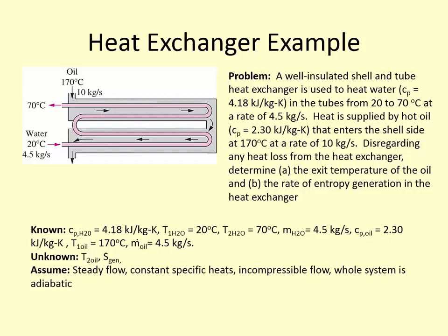So how would we go about trying first to determine the exit temperature of the oil? What will affect the oil temperature? How does it increase or decrease, or what do you think is going to happen? Okay, the water is affecting it. How? Okay, so if the water is heating up, then the oil should be cooling down, right? So we would expect the exit temperature of the oil to be lower than the temperature of the inlet.